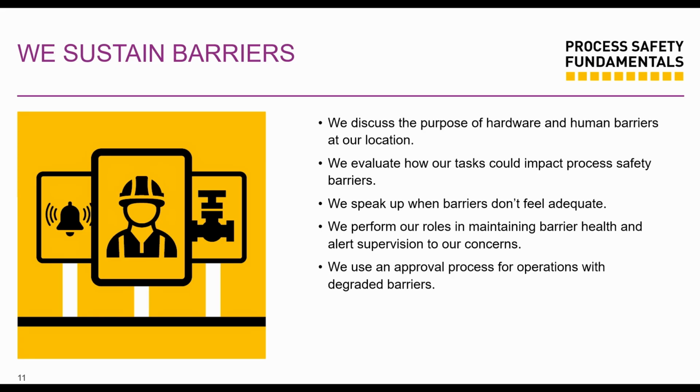when you're going to over pressure. That PSV is supposed to lift, but the PSV sticks because you didn't run your maintenance on it. And you have line ruptures, you have vessel ruptures, you have loss of containment. That PSV could have helped to relieve stuff to the right place instead. So those are examples of barriers. There are tons of barriers we could go into, but that's just a few.